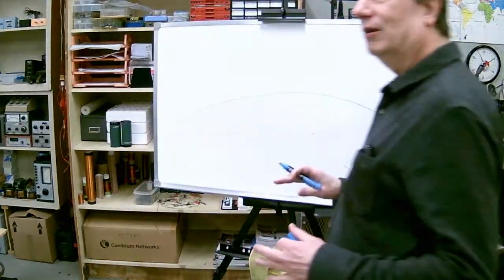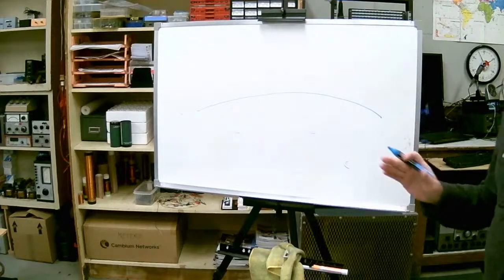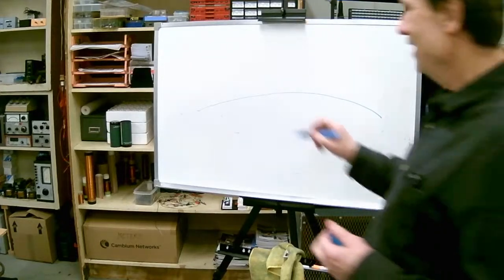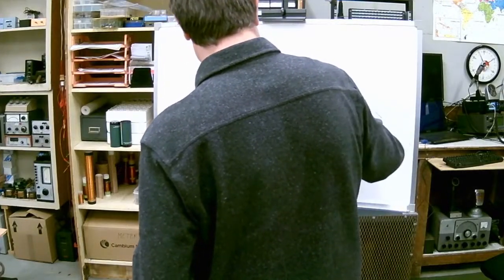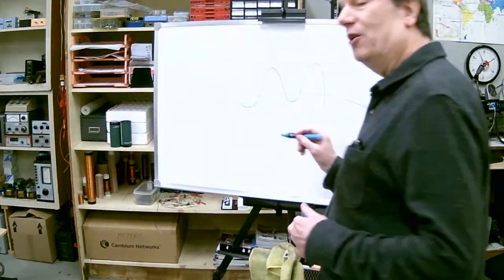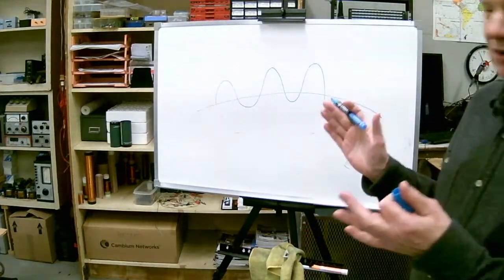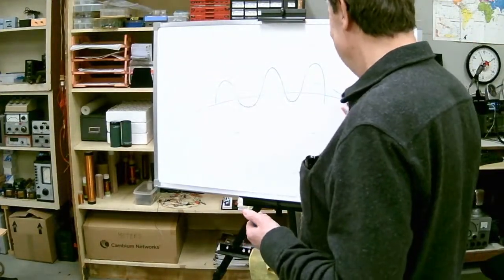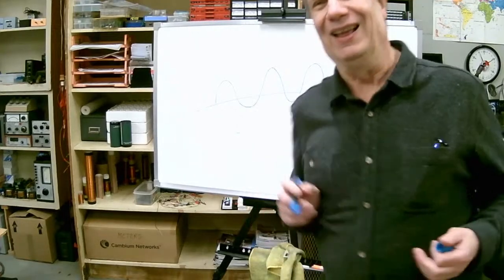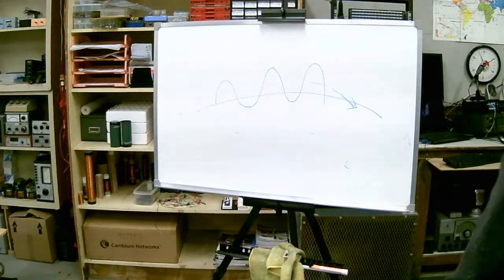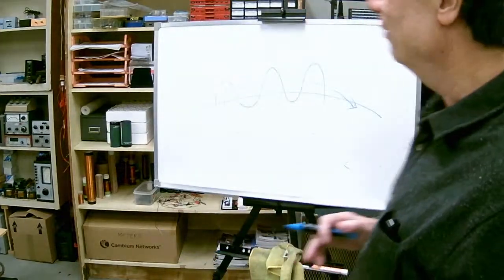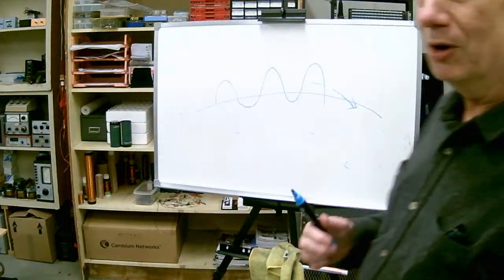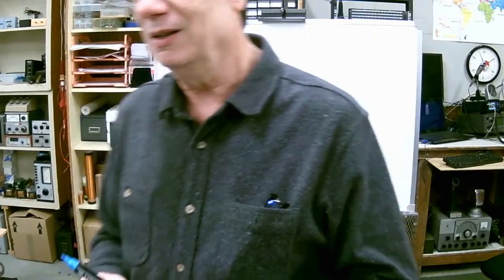The propagation velocity through dirt is a little bit slower than it is in free space. So if you have a wave that's propagating partially underground and on top, the wave that's underground is going to want to go a little bit slower than what's on top, so it's always going to want to bend toward the Earth, which is a good thing, which is how you can get long, beyond-the-horizon propagation on radio. So it actually clings to the surface of the Earth. That's called true ground wave propagation, and this is what most of your AM broadcasting relies on for anything beyond a few miles.